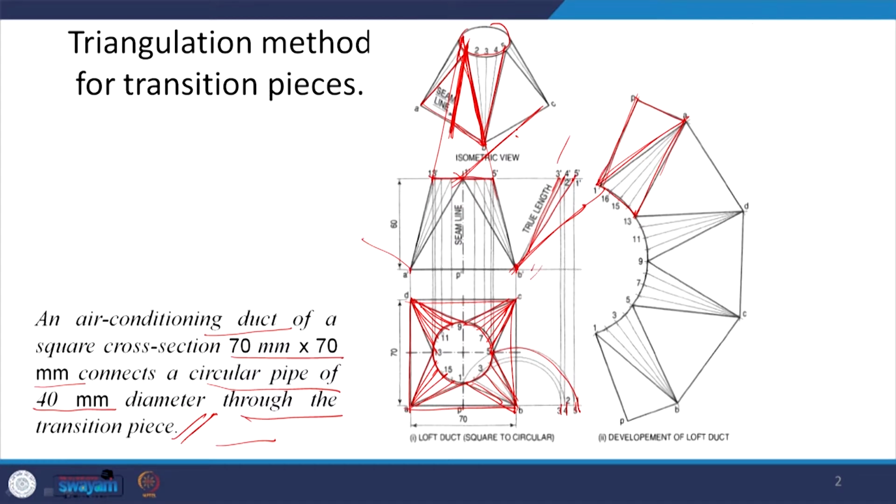So this part of the sheet will be developed like a radial line development. This is the part which is actually getting cut, which we get from here, and this is the rest of the part, and the circumference of this circle is going to come here.